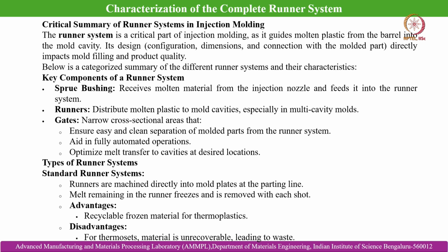So, it never freezes, the polymer or the feedstock material, that means metal polymer mixture or ceramic polymer mixture, it never freezes in case of hot runner. It only freezes for the component, and then the component gets easily detached from the runner.